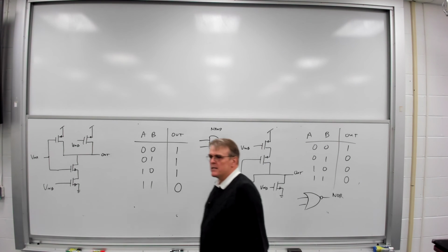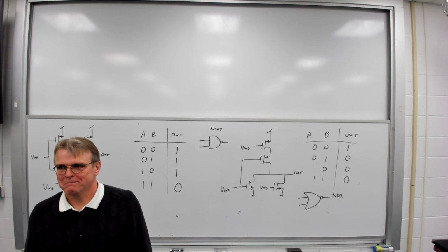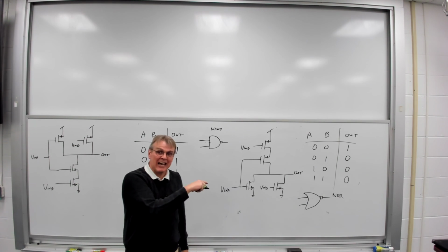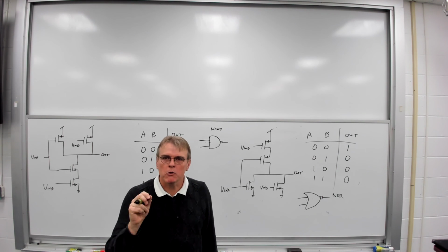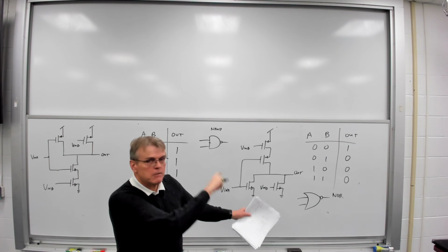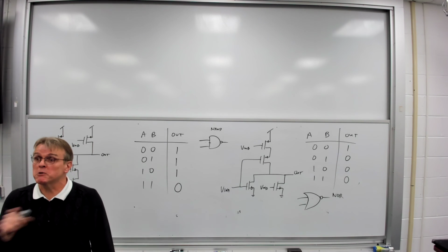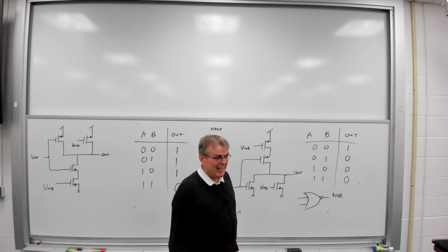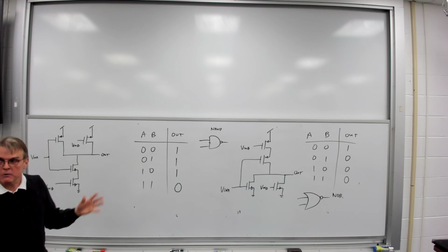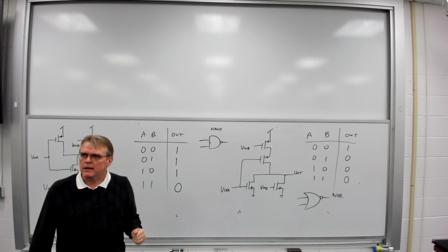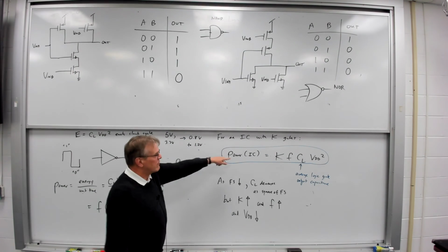Okay, guys, you now know more about logic gates than any computer science major ever will. Because you know what's on the inside. And not only that, you know why they work the way they do. Why does computer logic get faster and faster? Because of physics, because of RC time constants, because you guys took circuits 1. So you understand how the world works, okay? And you can still write software. But this really helps you understand. This is why digital logic works the way it does, built within the constraints of that equation.